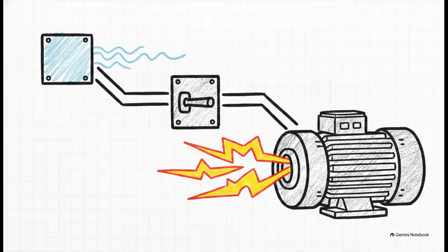But here is a critical engineering detail you definitely can't ignore. Because of this hierarchy, the power differences across these levels really matter. Down at the field level, those massive motors require heavy-duty three-phase alternating current. But up at the control level, your delicate PLCs are running on just 24 volts of direct current. So you absolutely must have a robust industrial power supply and incredibly strict safety protocols to bridge these levels safely. Otherwise, you're risking catastrophic failures.